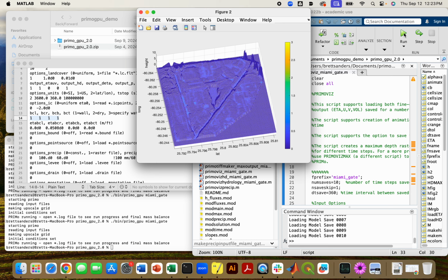So now we'd like to imagine the possibility that we're not using a constant rainfall, but some spatially and temporally varying rainfall. In order to get that rainfall data, you would want to go to a source of precipitation data, such as a source from NOAA or the Weather Service or other data sources that would give you gridded output files, raster formatted, spatially distributed rainfall information for different time instances. And you need to create really a set of raster layers showing the spatial distribution of flooding at different times.